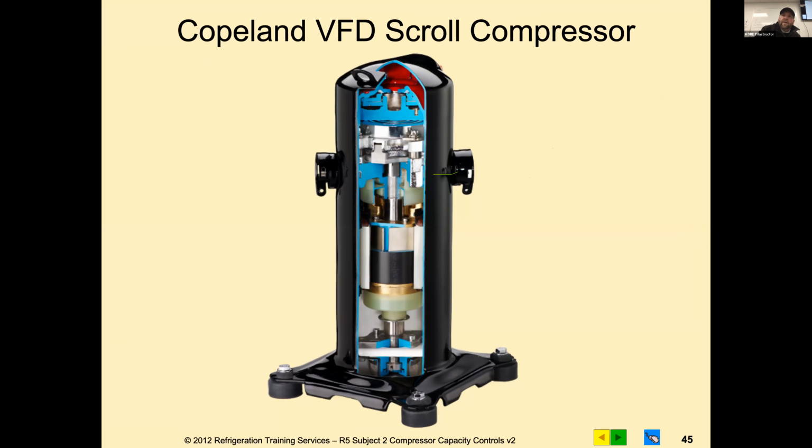If you have an Echelon controller, which is what Microthermal talks on, that's their platform, and you have a BACnet VFD, they won't communicate with each other. So whenever you're trying to scope a job for an application, that's the first thing you need to look at. If you're dealing with controls, make sure they're talking on the same protocol. If they do, we can work with the manufacturer and get it to work. But if they're on different protocols, they don't understand each other, they won't work.